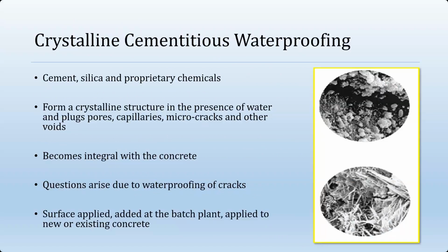Cementitious waterproofing, the crystallines we talked about. Again, these are topically applied. There are also admixtures, which are cast with the concrete. This is really looking at the topically applied. What they do is combine with the free lime that's pre-existing in concrete and reinitiate the crystalline growths, thereby reducing the capillaries or pores within the concrete. Now, obviously, since crystallines are largely a Portland-based material, they are very stiff. So if there is any substantial movement with this type of waterproofing, all bets are off.